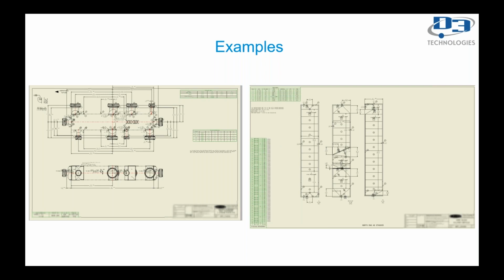But if you remember what we said with the vessel example and the nozzles, we're just saying, give me all the nozzles that are on this side and start dimensioning them and just offsetting them. And so this is literally one horizontal left dimension node, and this is another one, but it can create all 5, 6 of these dimensions, and then one more creates all of these.